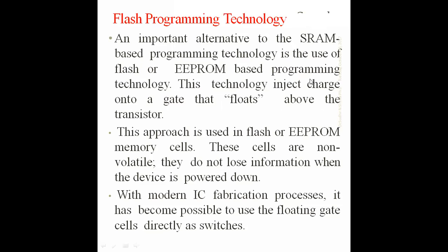Next is flash programming technology. An important alternative to the SRAM based programming technology is the use of flash, that is, electrically erasable programmable read only memory, EEPROM based programming technology.